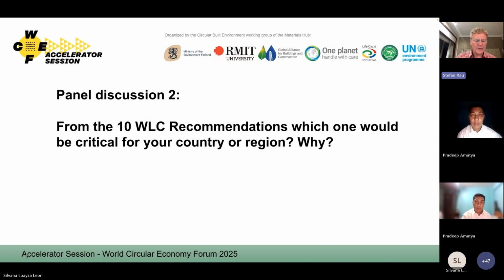The principle of redundancy is very directly related to design. When we design on the urban scale, we should design urban patterns that can be used for different kinds of uses, so that when the use that we're originally planning for changes because the demand and the market change and the city adapts to new economies, the design can adapt with these changes. The principle of redundancy also applies to the building level. If we are asked to design an office building or a residential building, we should already have the life cycle of the building in mind, where in the future the demand may change, and then the building can very simply be adapted to a new use if we have a redundant design.